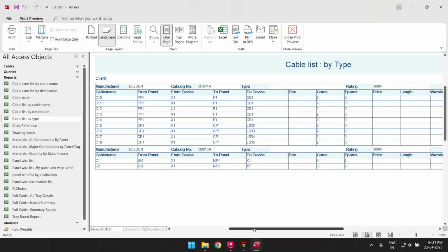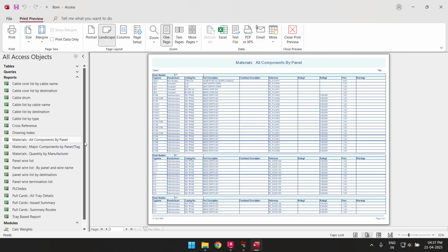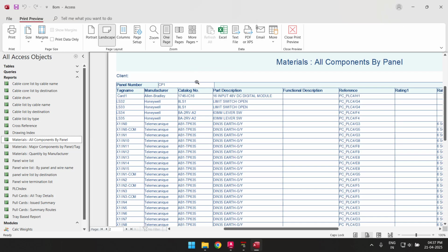A formatted materials list is provided in the EDS reports. The data is grouped by panel. This is useful for panel manufacturer. In formatted reports, you can obviously change the fonts, colours, spacings, and the general layout. However, you can also filter and group the data. For example, you could list only the instrument cables in the water treatment area.